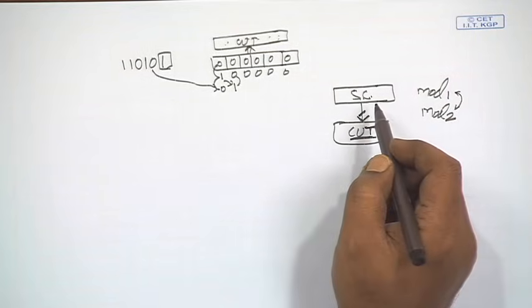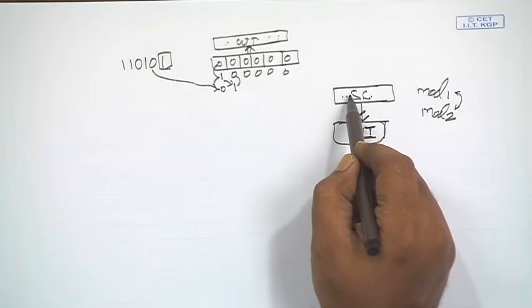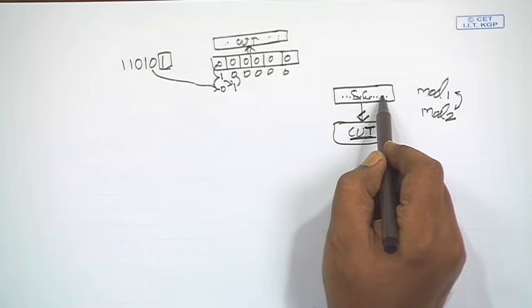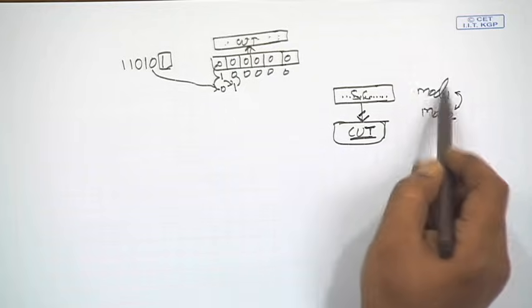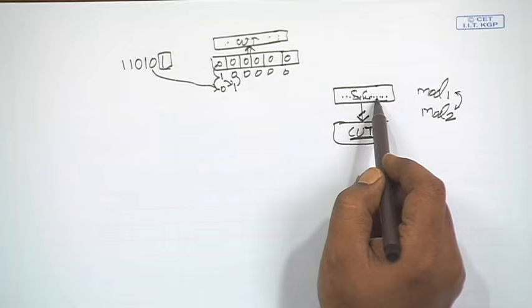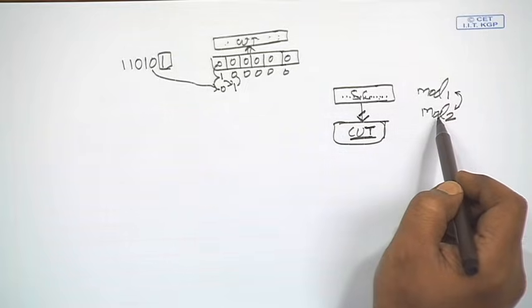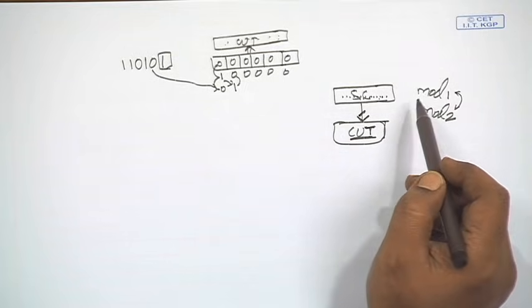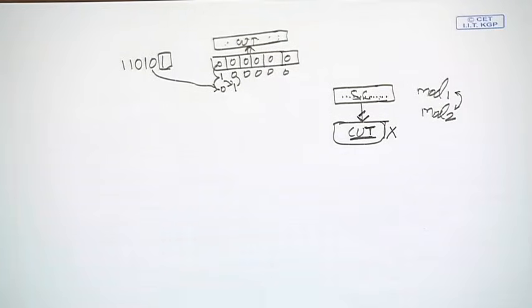Now, it has been seen that if you compute the transitions that are occurring in the scan chain itself, that is a good estimate. So, in case of modification 1, if we see that in that scan chain there are more transitions than in modification 2, then the circuit under modification 1 of the scan chain is expected to consume more power than the circuit under modification 2. So, we do not need to do explicit logic simulation of the circuit. That is not required.